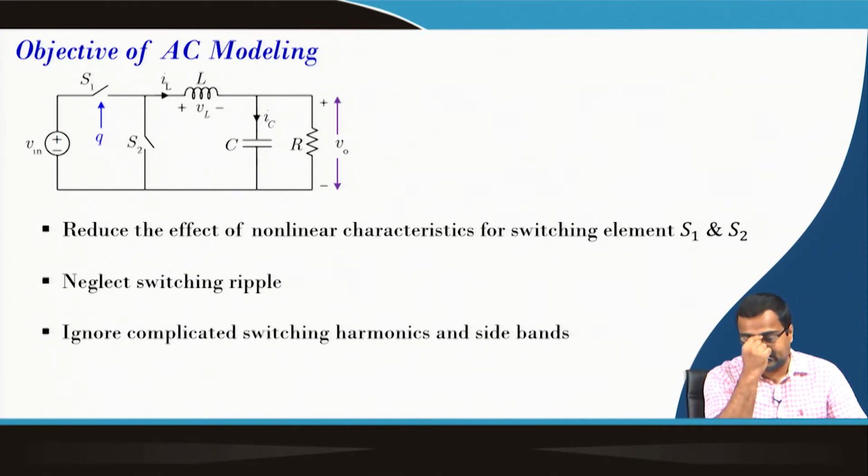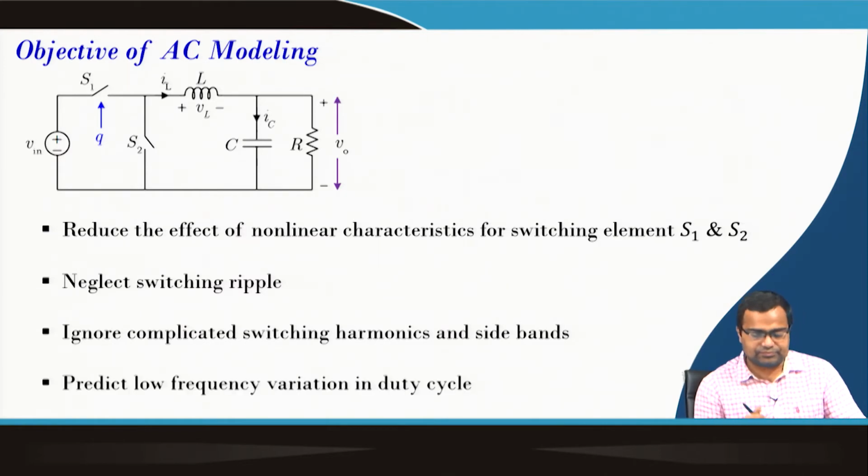That means, the converter is already running by a fixed frequency clock, but if we excite the duty ratio with a modulating frequency, we are interested in finding what is the response of the converter due to the injection of the modulating frequency, and we want to find out what is the component corresponding to that modulating frequency. Then we want to predict low frequency variation behavior in duty cycle.